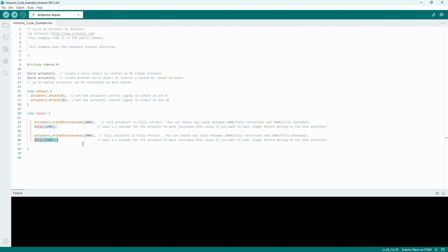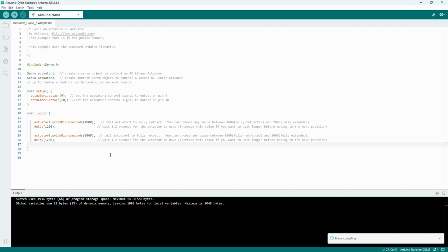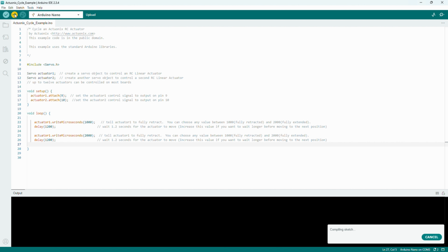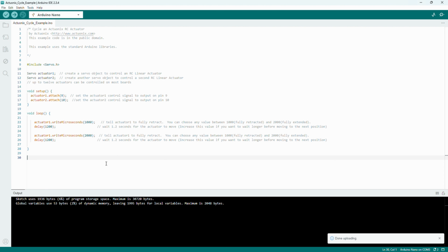Now for monitoring your tests, if you only need a rough measurement, you can record the start date and time and check for failure once a day as your testing progresses. Record the failure date and time when it occurs, and then calculate the number of seconds that have elapsed and divide by the cycle time. Remember to sum the two settings of your timer relay, as that is a full cycle. Your count will only be accurate within one day's worth of cycles, so this may be an issue depending on how long you expect this to last in your application.